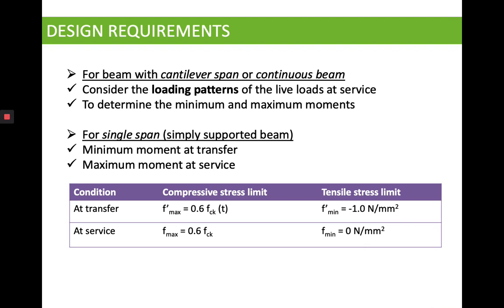If we can still remember, when we have a pre-stressed concrete structure that is subjected to a pre-stress force, when it is under service, under loading, we can see that our beam straightens. So at this point, we consider that we do not have any tensile stresses acting at the bottom of our beam. That is why the value here is equal to 0.